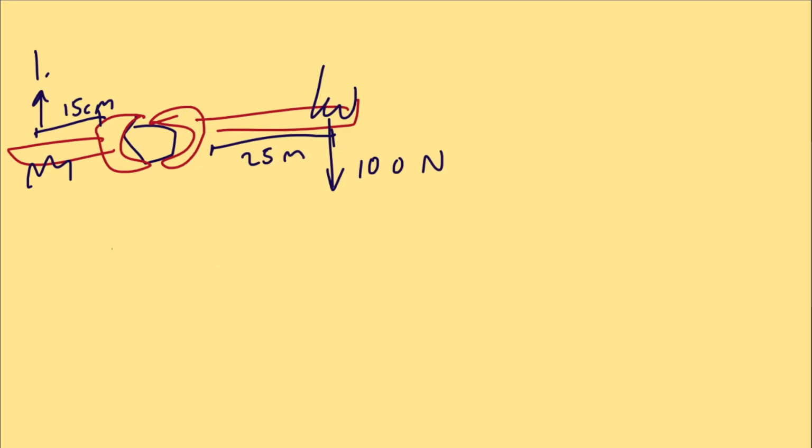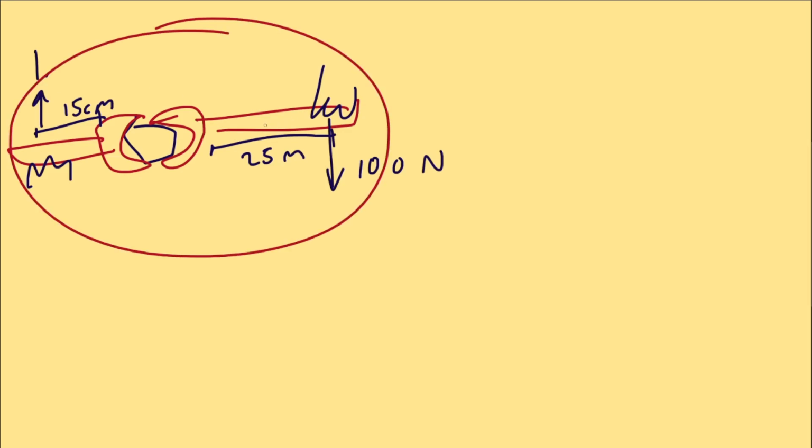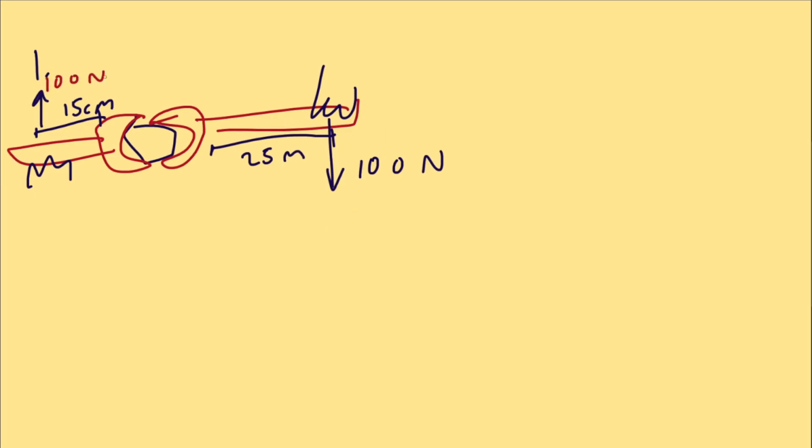So to keep the two wrenches in a straight line. Because right now, if we kept pushing like this and your friend pushed with the same or less force, then the whole system would start to rotate this way, because your friend has a shorter lever arm, so he has less torque. The question is how much force he has to exert to balance that. Let's follow our 4-step framework, which I'll put in the corner really quickly.